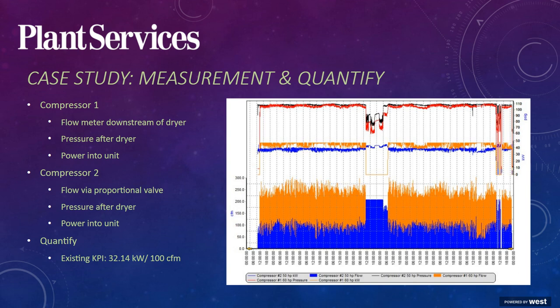Since compressor 2 was running in modulation control, flow on number 2 was measured by actually installing a vacuum transducer below the inlet valve but above the air end rotors. The discharge flow will fluctuate proportionally to the inlet vacuum, i.e. 50% vacuum represents 50% flow, and that's the way it'll nominally work unless there's some mechanical failure in the unit. A vacuum transducer could not be installed on compressor 1, so a flow meter was installed at the discharge of that system prior to the distribution piping.